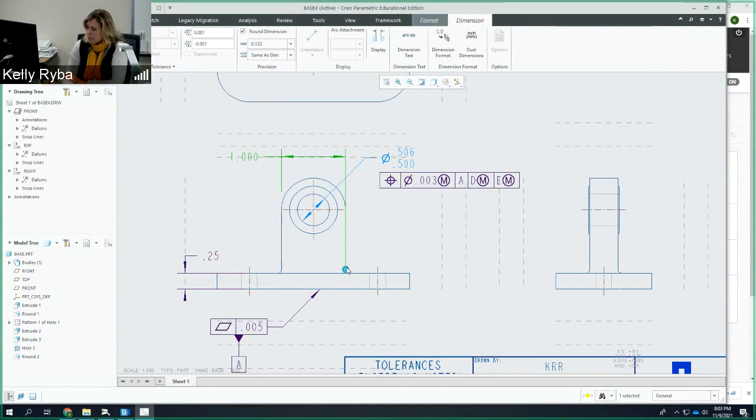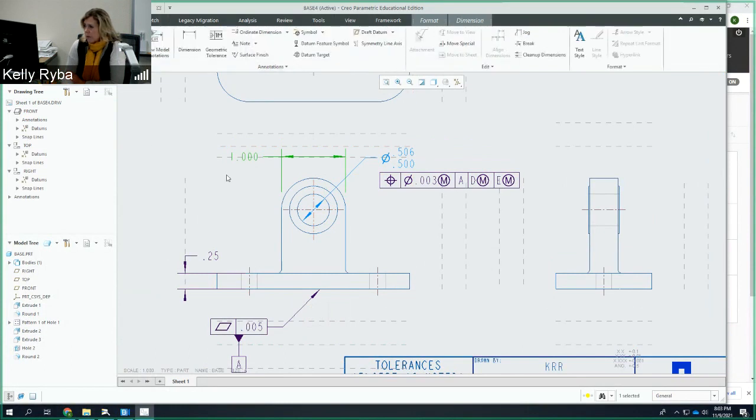I watch for this on your drawings because you can't have extension lines touching the actual part. So you have to create that gap between the part and the extension line, and now I've got that. Okay, so now I'm good. So I'm going to go back to annotate over here, and I'm going to just left click anywhere in the screen to get it to black so I'm not on that dimension.